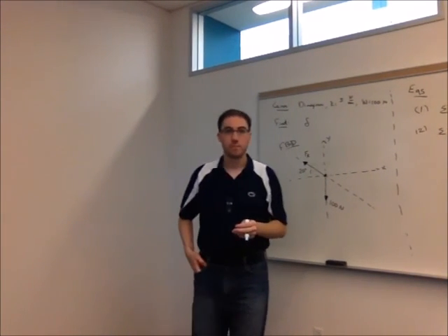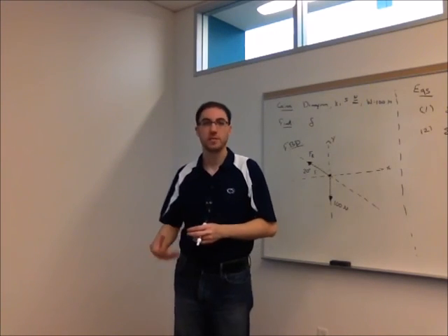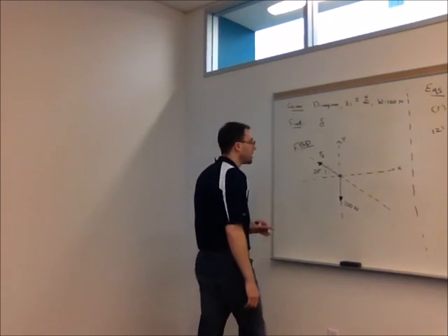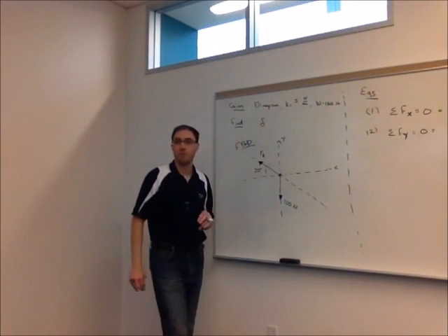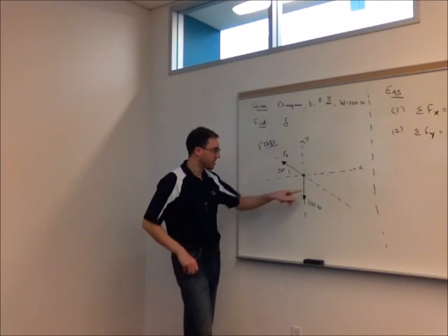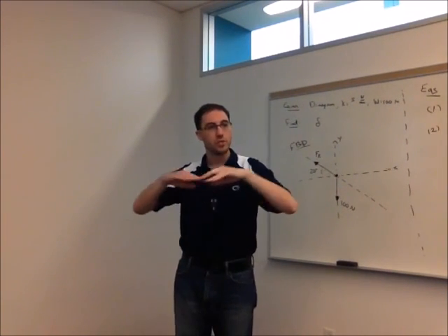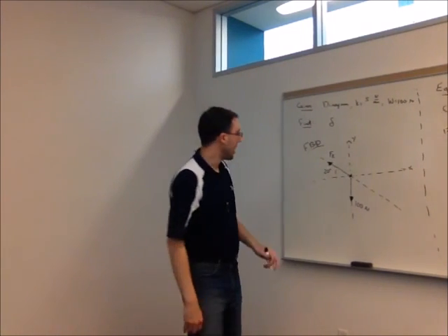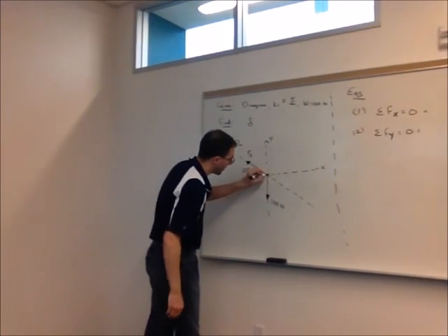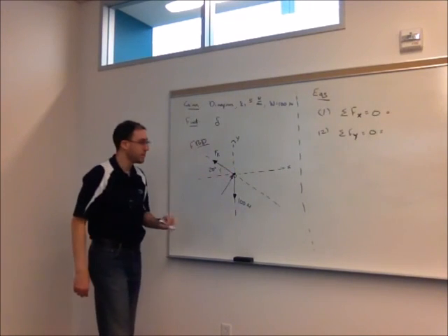Normal force. Right, so the force that keeps it from falling through the surface, that normal force. So in the picture, how do we represent the normal force? Perpendicular to, right, this 20-degree line. Normal forces are always perpendicular to the surface. So to this 20-degree line, right, that's where we have this normal force. So we know it's orthogonal to that line.